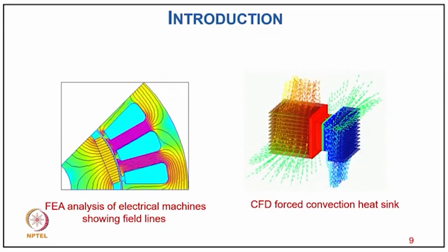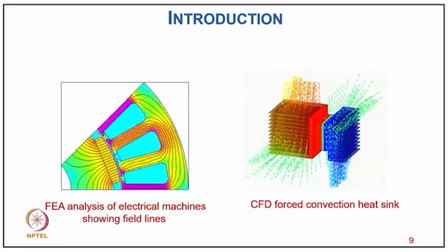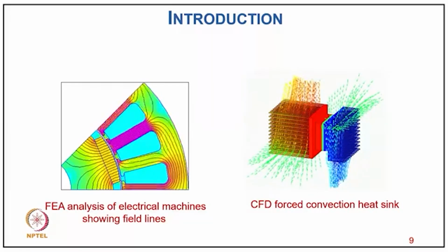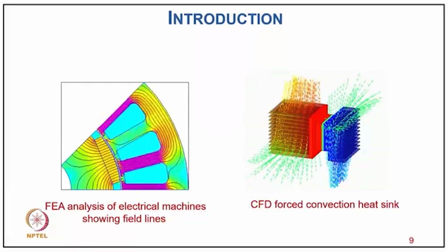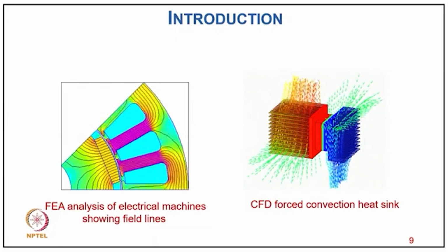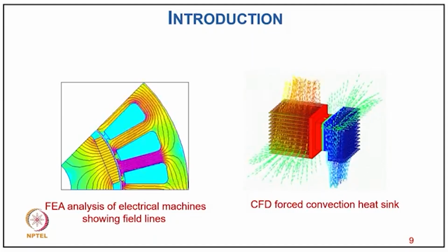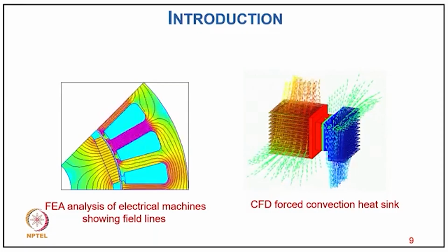We just conduct it when the design is finalized, to make sure the design does not have excessive saturation in some part, and that the concentration of the flux is not at some corners. Otherwise, it is just to check whether the machine is successful after designing with the basic analytical approach.